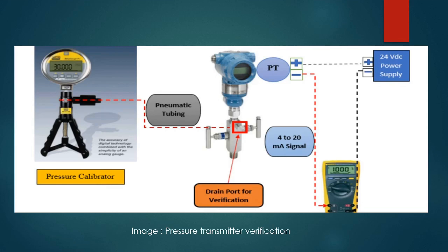After doing that, we need to ensure that appropriate lockout tagout has been done on the system. Then we need to conduct a thorough toolbox meeting, ensuring that people involved are thoroughly informed of the job to be done and also the risks and hazards involved. Also inform them of the PPE required in order to do the job. Once all this is done, we are ready to calibrate the pressure transmitter.